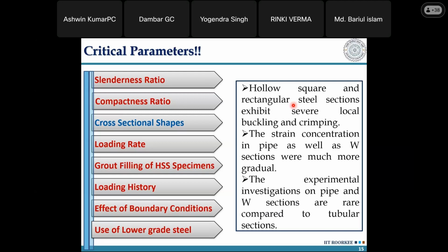But providing easy connections, I mean, the problem is with the I section. You can think that, okay, I can make out a connection right now. But to ensure that you get maximum energy dissipation, I have to make it buckle along the major axis. You can connect it along the minor axis of the I section. It will buckle around the minor axis, but then you don't have enough energy in the compression side.